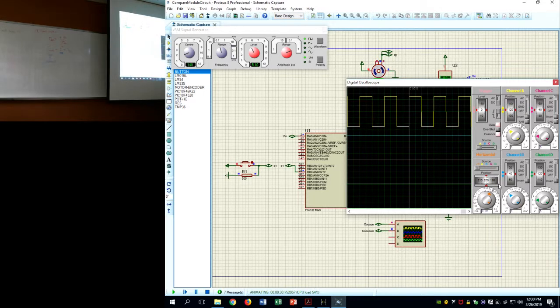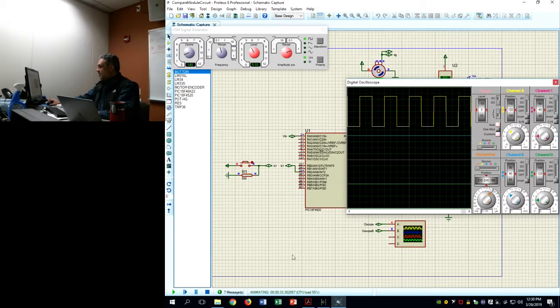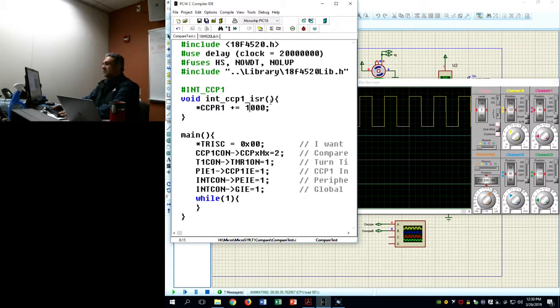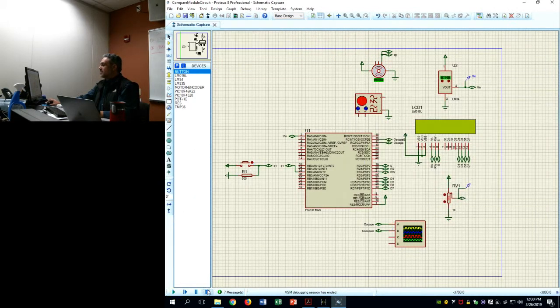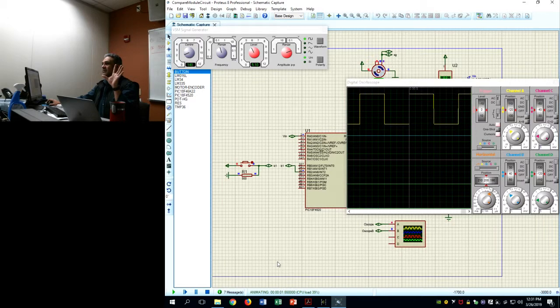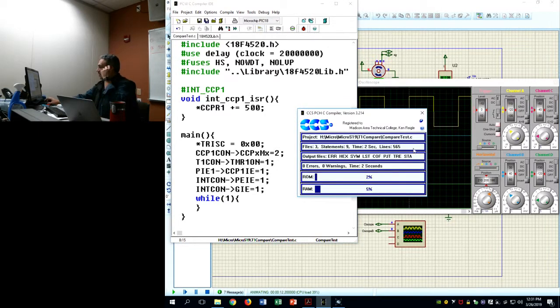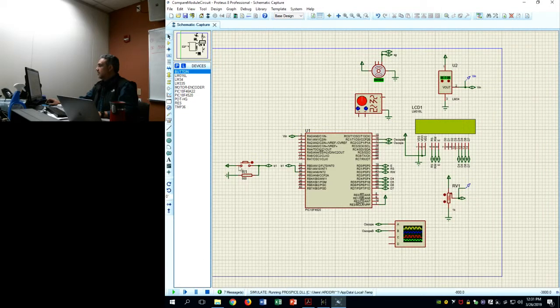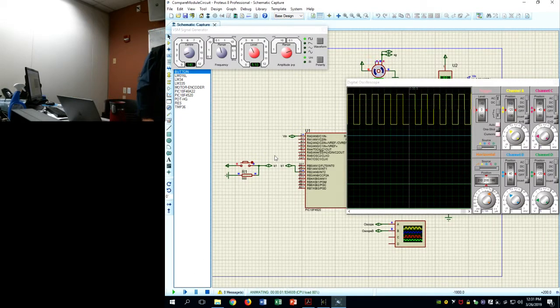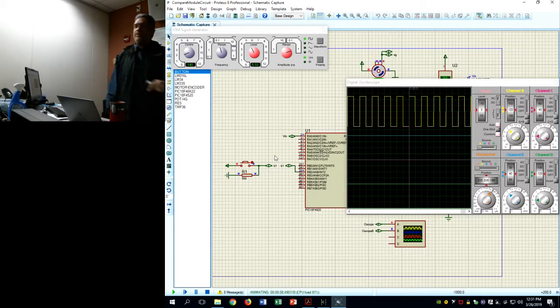You want to double the frequency, right? I'm sorry, half the frequency. So you can come in here on your software and you say, you know what? Forget every 1000. I'm going to go every 2000, let's say. So you go every 2000, look what happens to it. Opens up. See that? You can do this every 500. So maybe I should do this every 500. You see how much granularity I have? You can go every 501, every 502, every 503. Now the question is, what is that doing mathematically to my system? Let's take a look.